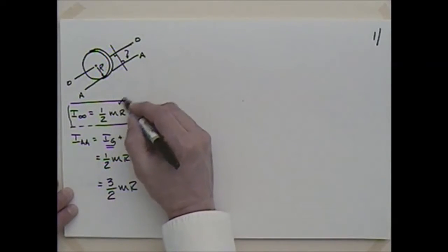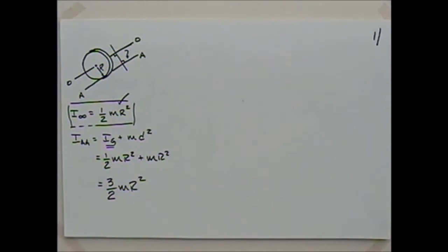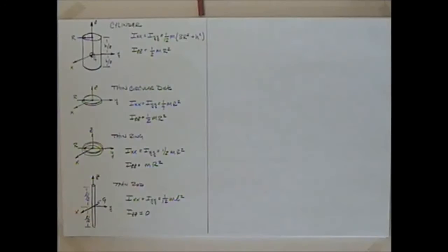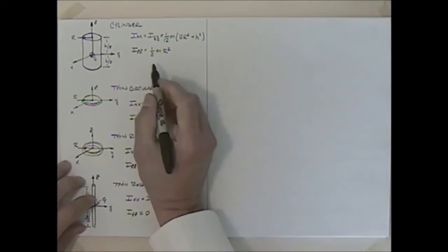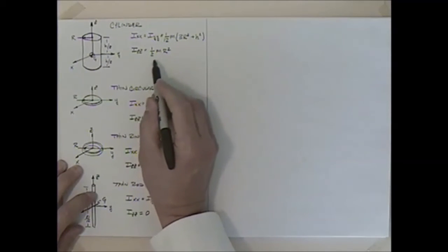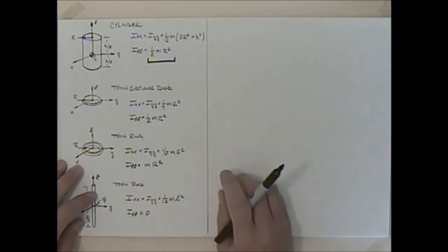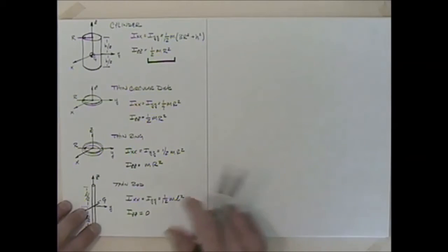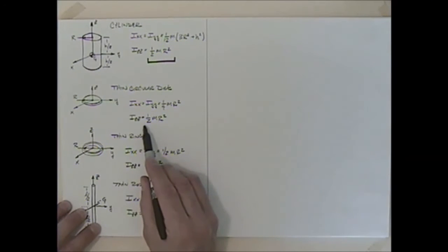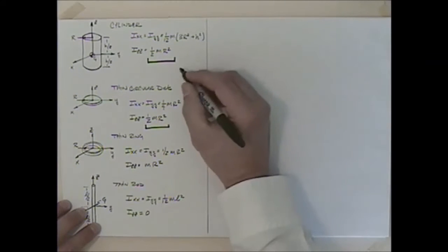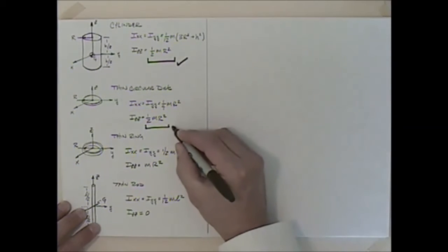And also, when you look these up, if you go back to some editions, in the past there have been some errors in the cover flaps of certain editions of the textbook in terms of the mass moment of inertia. It was predominantly with this one here for a cylinder, this 1/2 mr squared. I think there are certain editions that have mr squared, and there may have been some problems with this circular disc that had the same value. So if you've got a textbook, you may want to double check those.